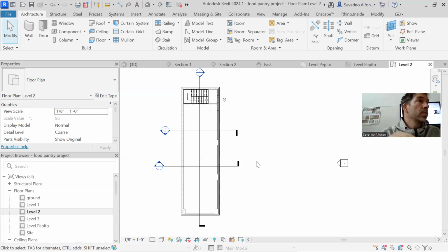And that's walls, floors, roofs, ceilings, things of that nature. A door is a family, comes from outside. A window comes from outside. Even a structural column comes from outside. All these things come from outside. A railing and all these things. The stairs are a bit more complex. They depend on 5 or 6 or 7 different families coming together, like the railing family with the steps family, with the landing family. So there are a number of families that shape a stair. So it's a bit more of a complex thing.